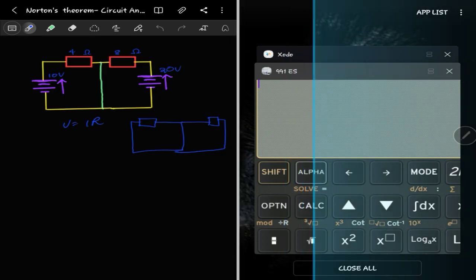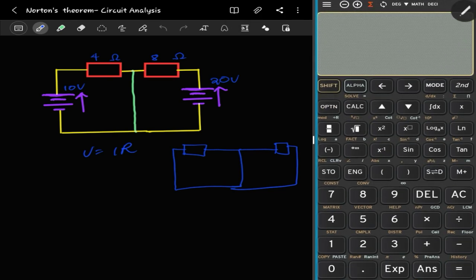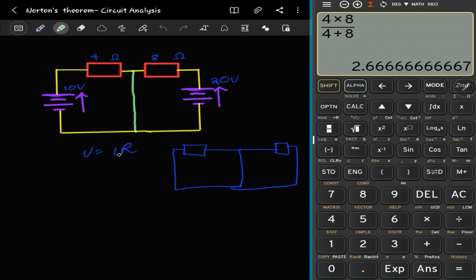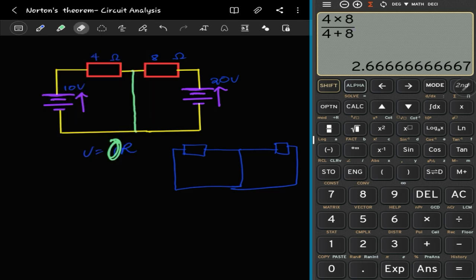the resistances here are just 4 and 8, right? The simple circuit that we have right now, the resistances there are just 4 and 8. Okay, so if it's 2, product over sum, so 4 times 8 over 4 plus 8, and that will give us the effective resistance here. Because we are following this basic equation, we said our aim is, in the end, to be able to find the current here, right? The question actually asks for the voltage across the 2 amperes, right?